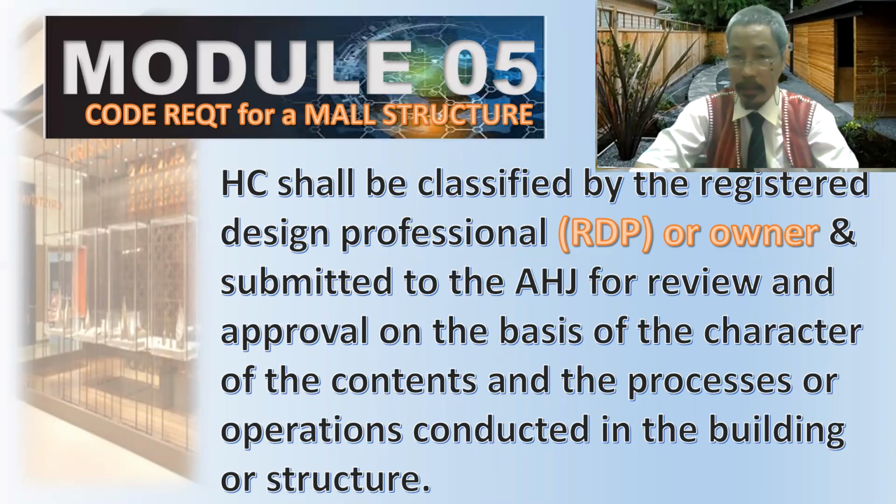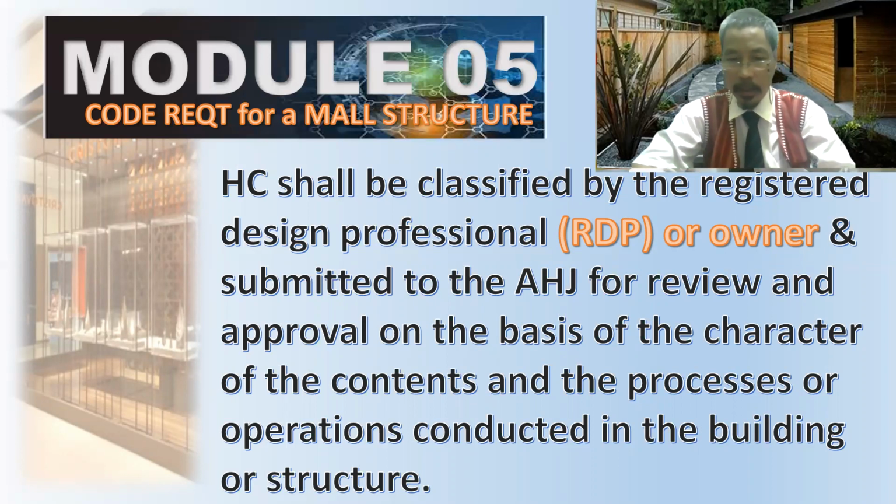So the burden to evaluate what hazard of contents the area has is for the owner or the registered design professional to determine it, and submit it to the AHJ or the authority having jurisdiction for review and approval on the basis of the character of the contents in the processes or operations conducted in the building or structure.